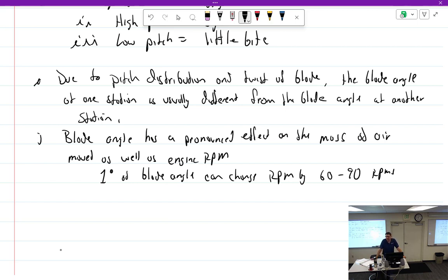So doing the annual on the 150, right? Feet on the brakes, wide open throttle, carb heat off, mixture should be at best power, which it usually is around here, wide open throttle. And I'm going to see where the RPM goes.